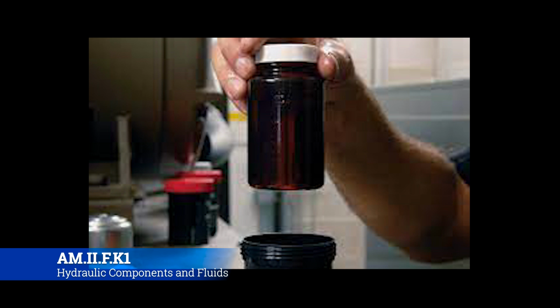And then you'll also do draining services on a pretty regular basis. But I don't want to get too far into that because filters are kind of their own class. But I will talk about some drain and flushes. Typically, whenever you have any sort of contamination issue, or honestly any sort of maintenance issue with any fluid system, one of the first things you're going to do is drain all the fluid out. Then you're going to take the filters out, put a new filter in, and then reservice it. You may even drain it all out and then flush it with the right type of fluid multiple times, and then you finally service it for the last time.